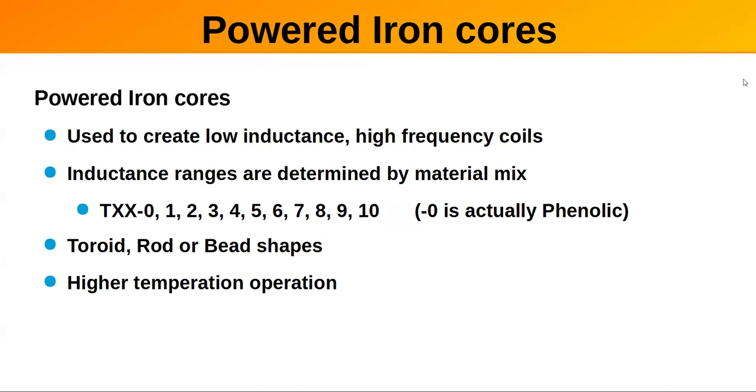See, powdered iron, like I said, they're lower inductance, but they typically allow you to operate at much higher frequencies. When you get to very low inductance and very high frequencies, you typically go back to just an air core because you're only looking at a few turns.